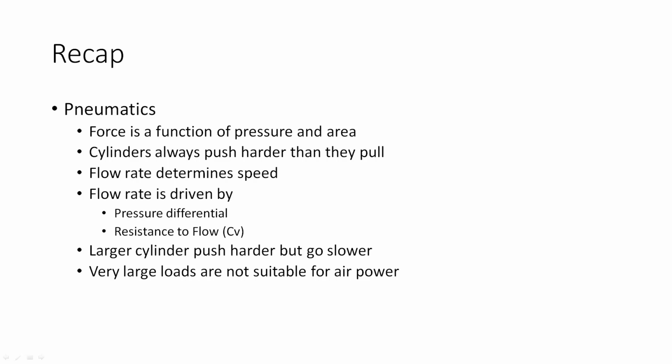A big cylinder pushes hard, but it goes slower. There's no free lunch here. The amount of power I can provide, or the rate of doing work, is really related to the flow rate. And the last one is very large loads are probably not suitable for air power. There's just not enough onboard compressing, storage, or size in the lines to make a massive amount of force using pneumatics. So think of a different mechanism. If you're looking to generate a lot of linear force in a rapid time, air is probably not it.